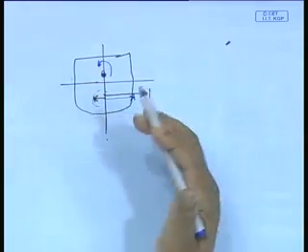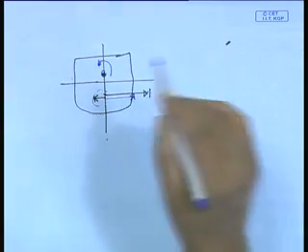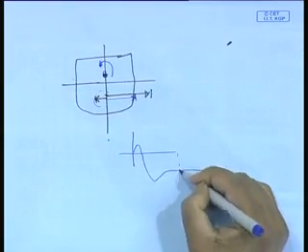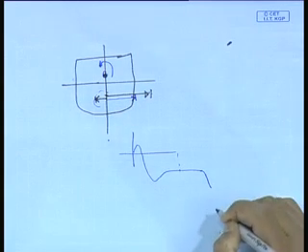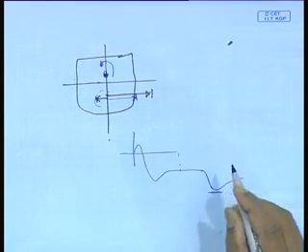suddenly, not slowly; we are talking of this time element. Then suddenly this much force will act, which means the moment acting here to turn is suddenly increased. Therefore, the ship is going to have a snap roll, and it might be more than the stability angle.